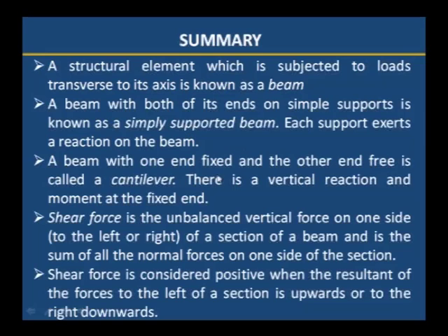A beam with one end fixed and the other end free is called a cantilever beam. Second one is the cantilever beam, which is fixed at one end and free at the other end. There is a vertical reaction and moment at the fixed end. Shear force is the unbalanced vertical force on one side, to the left or right of the section of the beam, and is the sum of all the vertical forces on one side of the section. Shear force is the unbalanced force acting on the right side or the left side of the section.